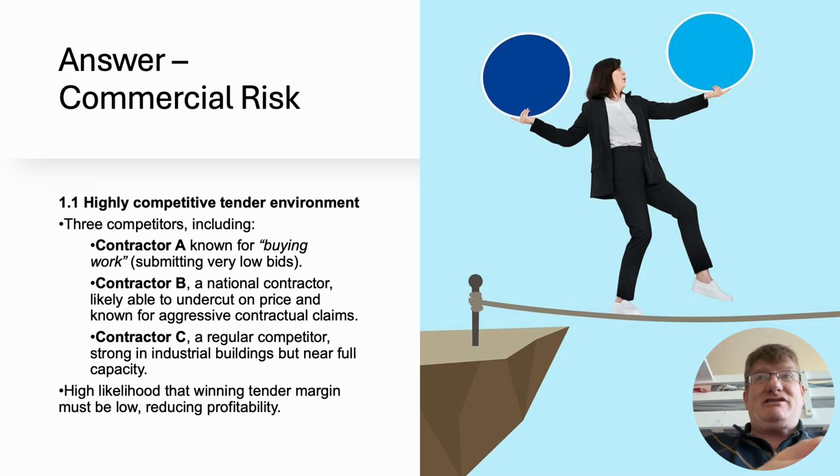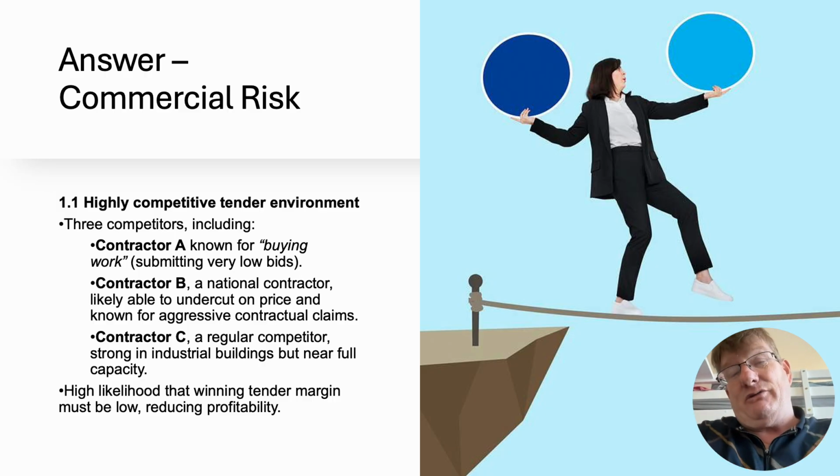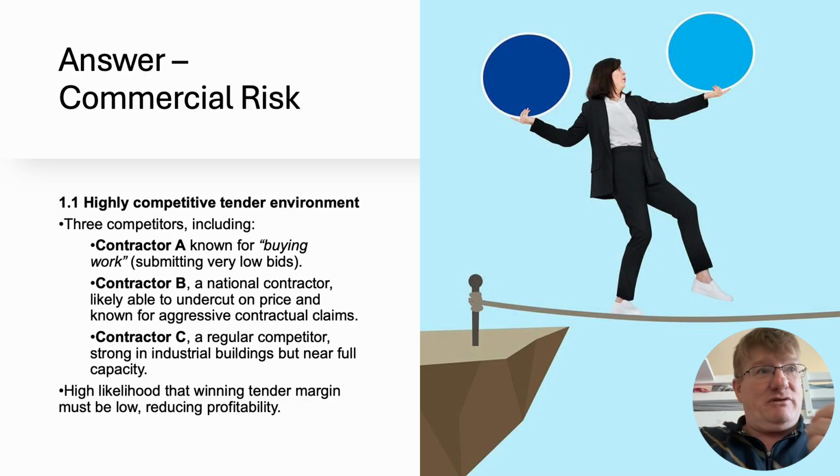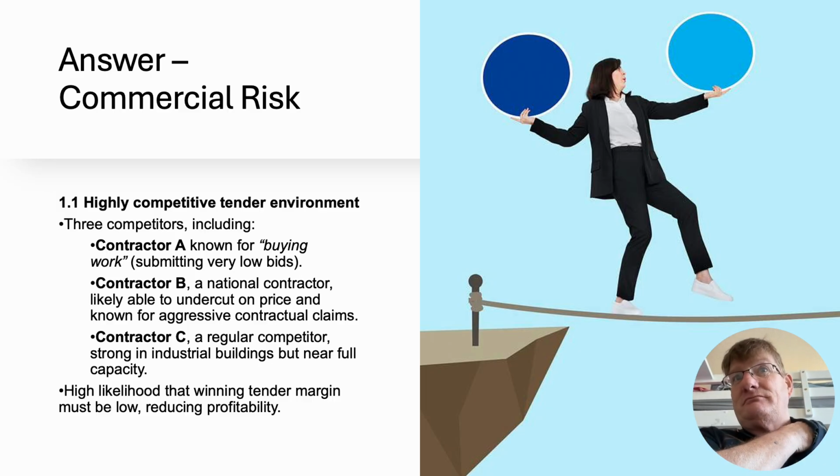However, ultimately the budget is going to change to the actual estimate produced by the contractor or the subcontractors, because they have to take into consideration up-to-date prices and the type of contract it is: fixed, fluctuating, lump sum, target price, cost plus. All of these things will weigh down the contractor with regards to commercial risk. And the contractors and subcontractors will take into consideration a risk element for them.